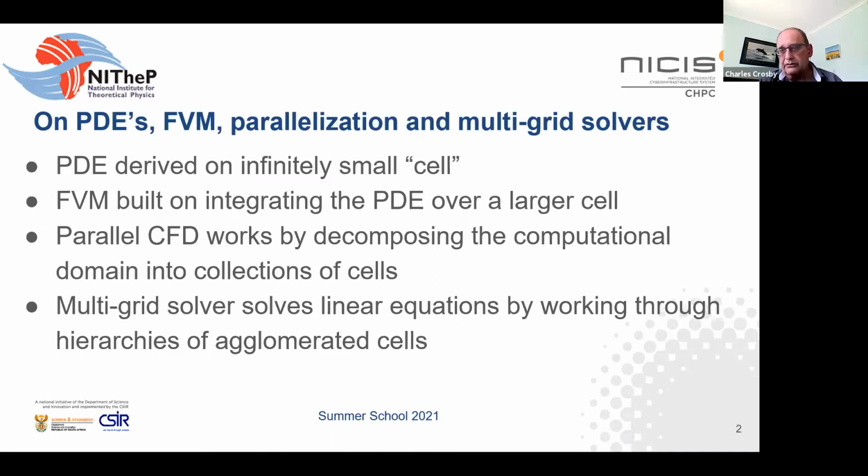So for fluid dynamics, if you're going to be working in fluid dynamics and you want to write your own stuff, one place where you can start is OpenFOAM. OpenFOAM is a collection of libraries that you can use to write new solvers. It wasn't originally developed as an out-of-the-box tool. It was developed as a way of making it easy for you to develop your own solvers. So you've got building blocks where you don't even need to think about the parallel processing. That's already been built in. You don't need to think about the input and output. That's already built in. You only need to think about your equations and what schemes you want to apply to your equations. So those frameworks exist.